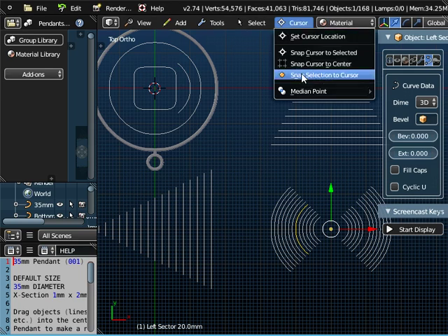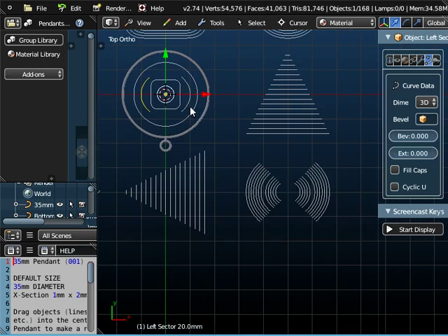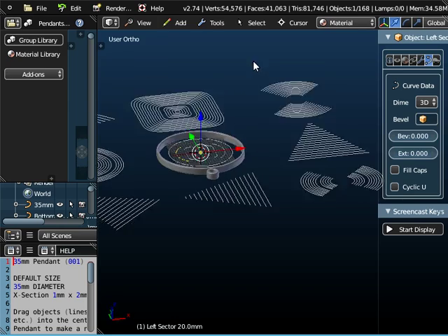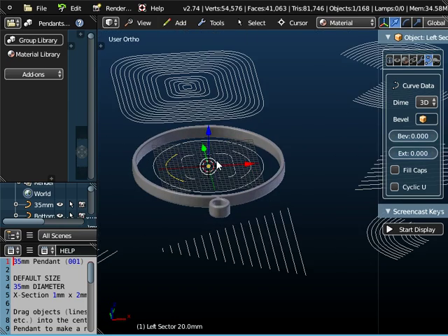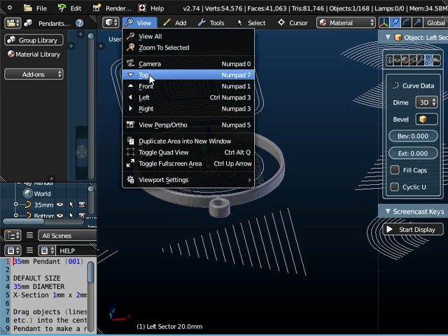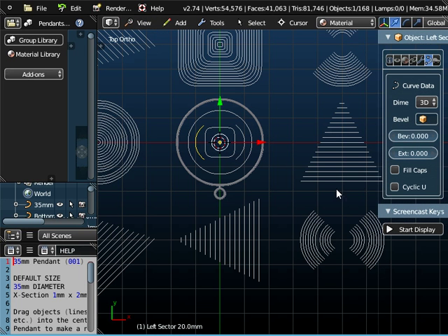And if I just snap that there, that just makes it symmetrical. Now we can't print a pendant like this at the moment. For a start, these items in the middle have got no thickness, but they're also not touching the pendant on the outside. So one of the features of this particular thing is that we do need to have a line that goes to touch all the different objects in the middle plus the pendant itself.